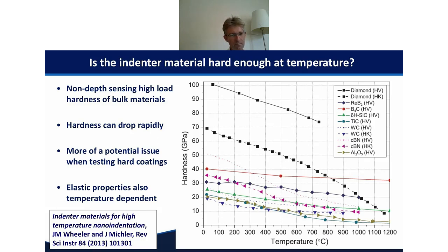As well as the hardness of indenter materials being temperature dependent, their elastic properties and their Poisson's ratios are also temperature dependent, but these are much less temperature dependent. But it is useful to incorporate these temperature dependent properties in your analysis when converting from the measured reduced modulus into the sample Young's modulus at temperature.